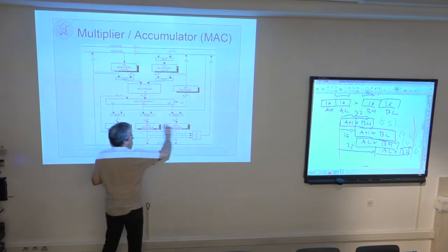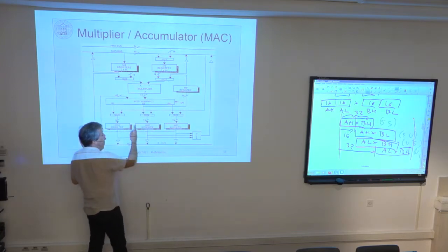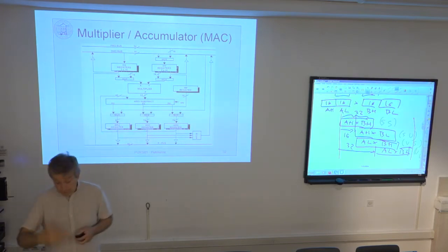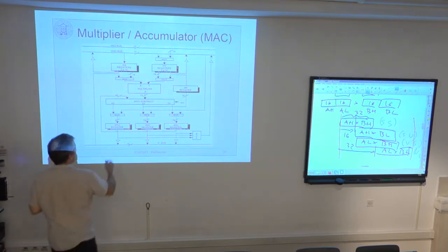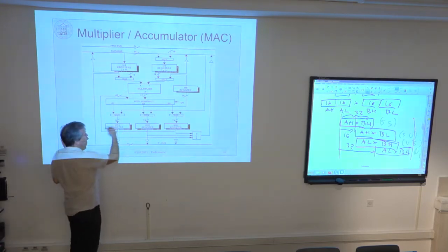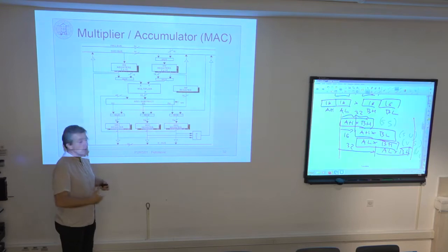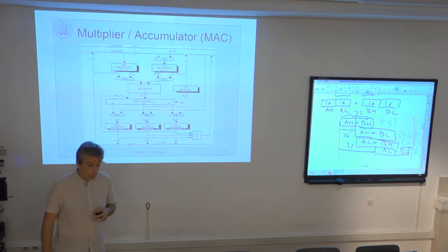It means all of these registers are full. MR1 and MR0 are full. So the leading bit, if they are positive, is 0, 1. Leading bits are 0, 1, and so on. And if I want to accumulate such products, I must somehow be able to capture all of this carry that goes from the MR1 and MR0. So with this addition, this extension goes into MR2.